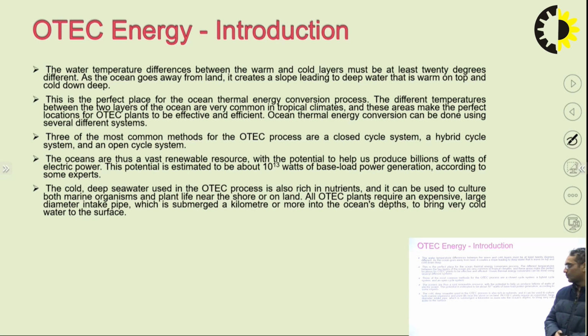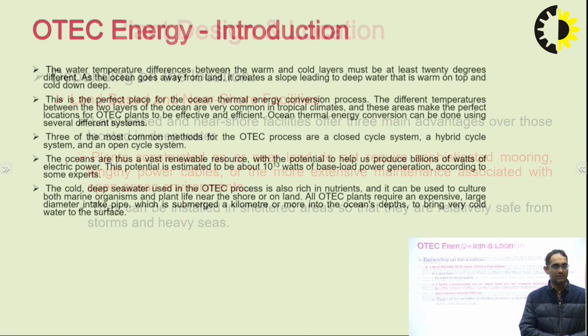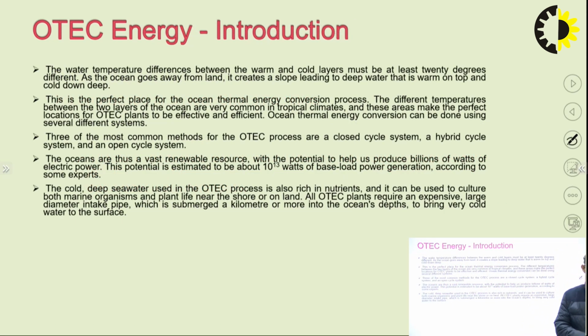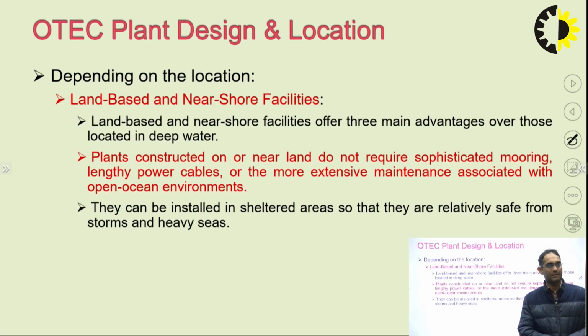And the cool deep sea water used in the OTEC process is also rich in nutrients, and it can be used to culture both marine organisms and plant life near the shore or on the land. All OTEC plants require an expensive large diameter intake pipe, which is submerged a kilometer or more in the OTEC depth to bring very cold water to the surface. Then depending upon the location, land-based and near-shore facilities.